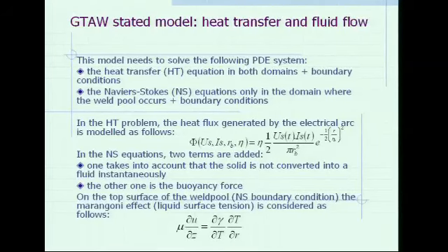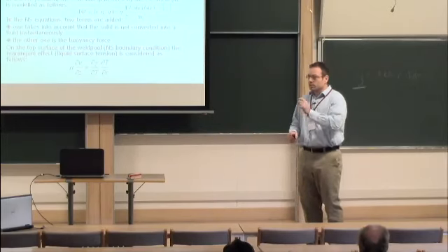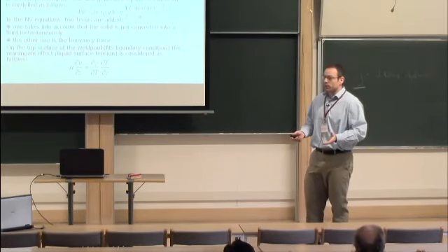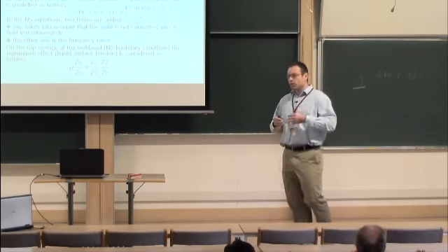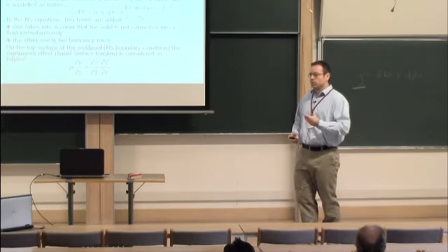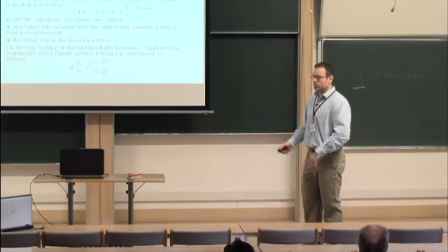I forgot to say something. Basically, in the welding industry, when you set up a welding process, you have some standards. What I mean is they have welding knowledge, how to weld these two metallic parts. So if it is a thickness of 10 millimeters, you will use a range of, for example, 100 to 200 amperes. So it is lower than that, 100 to 150 to weld it. After, I don't know if it is better to use 120 or 130 amperes. And the problem is, if you add more heat input, you can change the material properties. So what you want is to optimize it and get a better value for this.